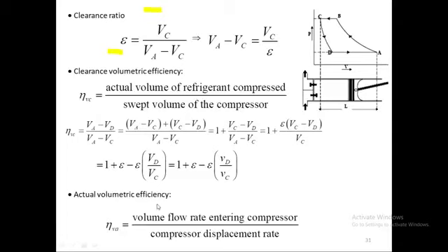But in actual volumetric efficiency, we consider losses also, losses due to leakage, of course, because there will be some piston ring here, so some of the refrigerant can escape, and there are also losses from the valves. There could be some loss as the valve is closing or when the valve is opening, or simply from the sealing of the valve there could be some losses there.